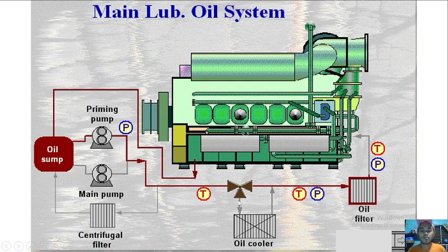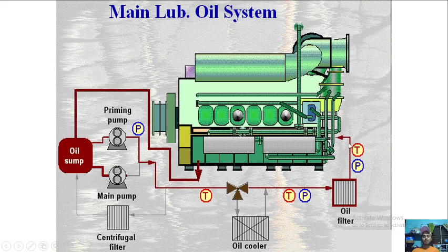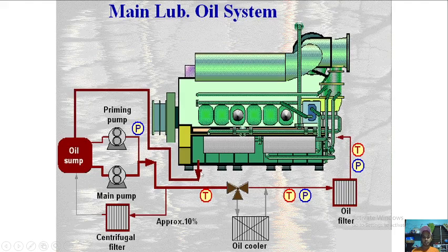If it needs cooling, it will go to the oil cooler, but if it is still cold and doesn't need cooling, it will bypass, going to the oil filter, and then entering into the engine. After the engine, it will go back again to the oil sump, and the priming pump is used only during startup.